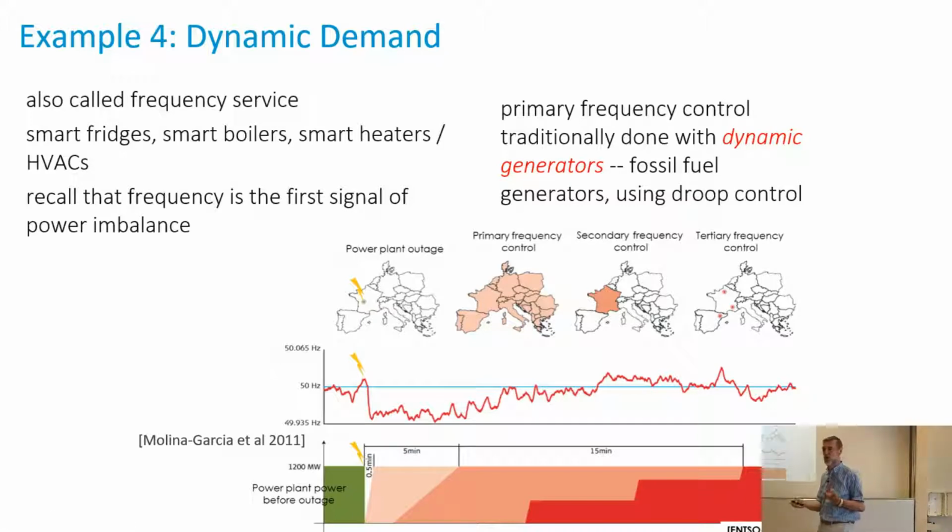You forecast the load. You know there is a risk of anything going wrong. So what you do is you have a bit of reserve. So of course you put more generation in place than what is strictly needed, so that if at least one of the major generators goes away, you'll be able to recover. Plus you put all this system of reserves here.